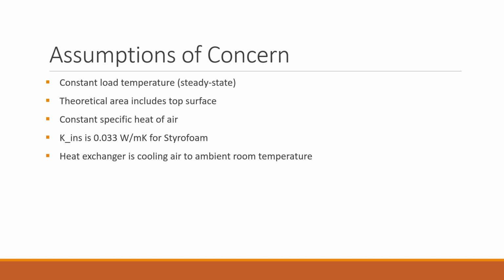Next, we assume that the specific heat of air is constant. Although this is not always the case because specific heat is affected by temperature and pressure, it is a good assumption. Next, we assume that the K insulative value is 0.033 watts per meter Kelvin for the styrofoam. This is a good assumption, although it could be better if we were to ask the supplier for their value.